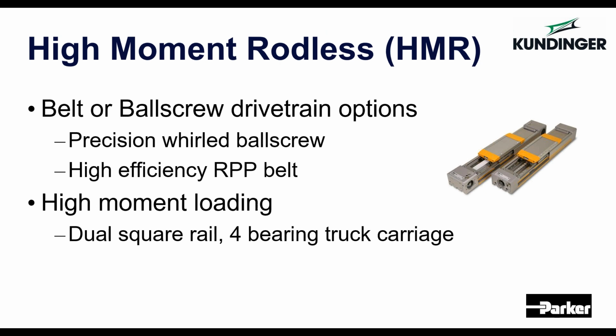Rolled meaning we're just either heating the screw up and hot rolling threads into it, or cold rolling threads like you would make any other fastener. Whirled means you're basically machining the screw, or cutting it like you would a gear, meaning it's not as costly and long of a process as grinding, but it's a lot more precise than a process such as rolling.